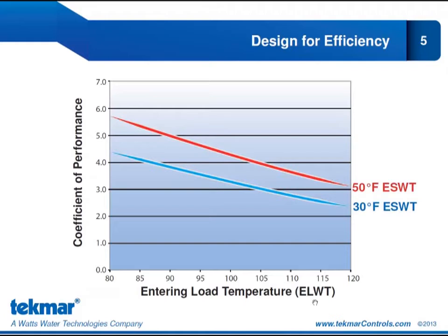So remember, even if you have the best control solution, if we are not working with the optimal entering load water temperature and the optimal entering source water temperature, then the controls will not be able to impact the efficiency the way they were designed to do.